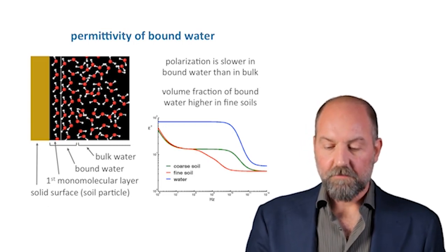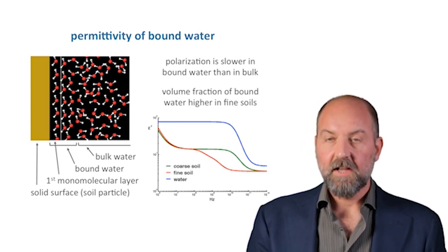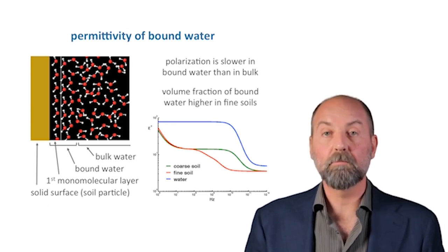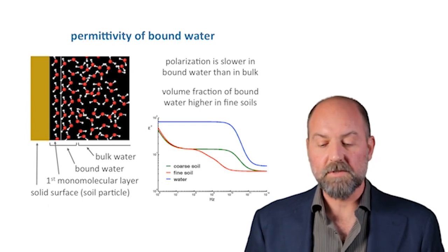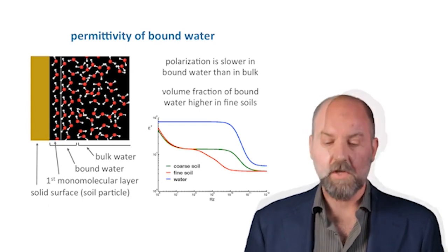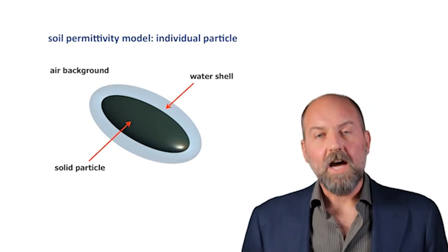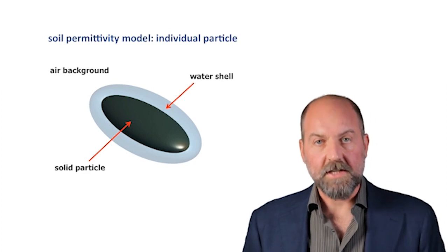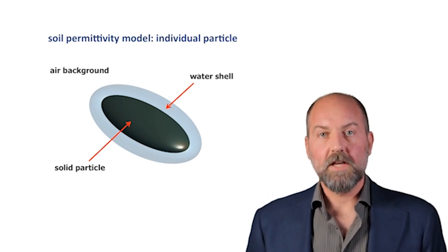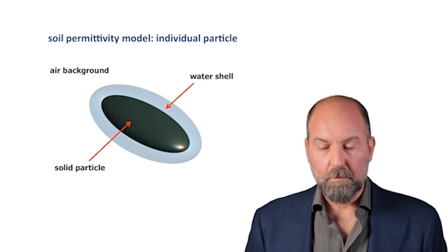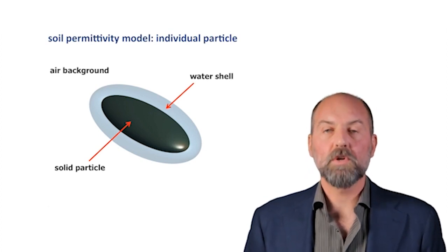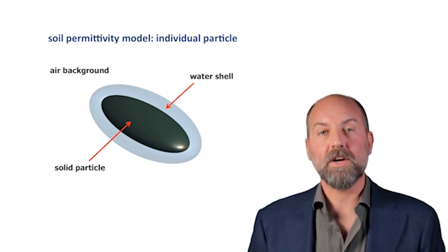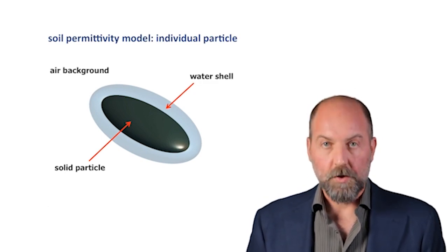Well, as you can see, for fine soils, we have the relaxation frequency much smaller than what is observed for a coarse soil or for bulk water. In order to quantify the effect of the surface or the effect of soil textures, just like effects of the other additional factors we will be discussing here, it is important to avail ourselves of a model that can predict somehow the macroscopic permittivity of soil.